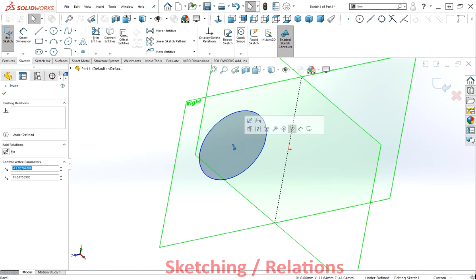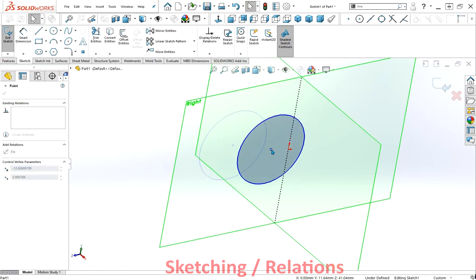So, if I want to do that, the first thing I would thoroughly recommend, if you're starting with a circle in this case, is locking onto the origin. There's a couple of ways I can do that. I can either click and drag that, and you can see it associates it, and that little tiny yellow icon means that it's been constrained or snapped to that point, and it'll be forever at that point. It's like a design rule, you can't change it. Well, you can go back and edit it, but unless you edit it, it will stay the same.